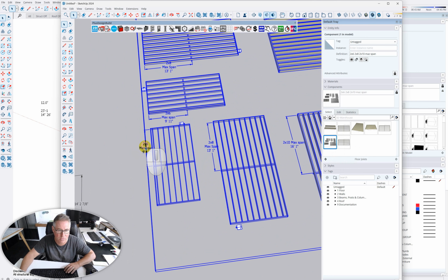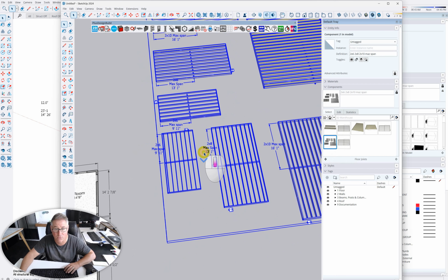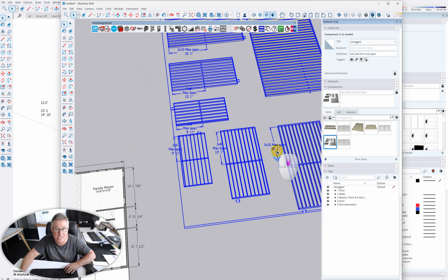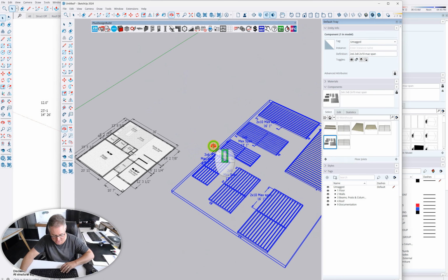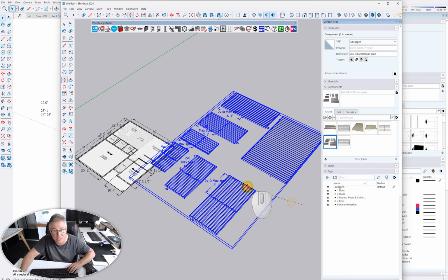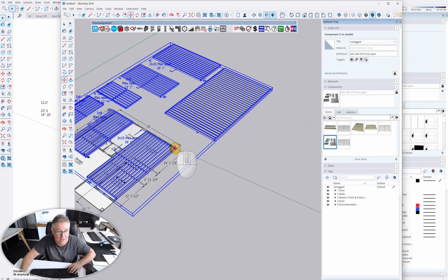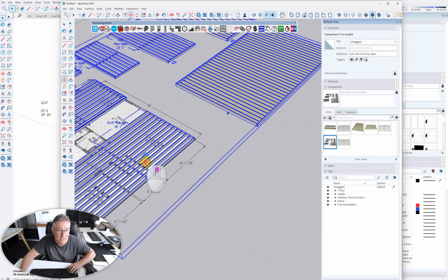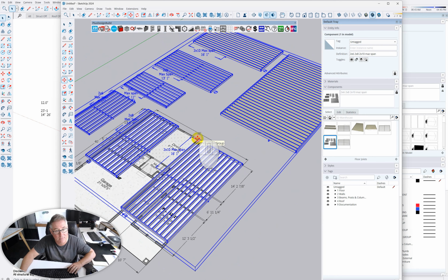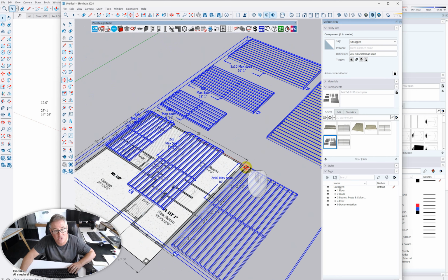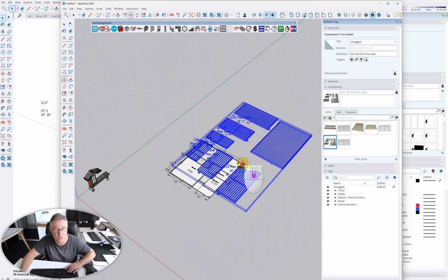So you can see I've got 2x6s spanning 9'11", 2x8s spanning 13'1", and 2x10s at 16'1". Now I can simply read the dimensions on the plan, but even easier, provided that plan is to scale, I can just bring these over to here and say, okay, which one works best? So the 2x10 works, it's over-spanning from that nib wall there. 2 by 8 is too short, therefore it'll be a 2 by 10.